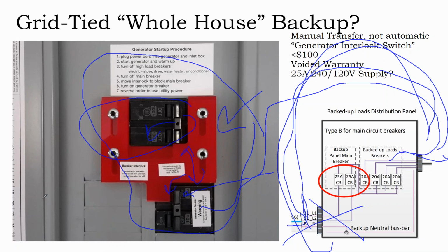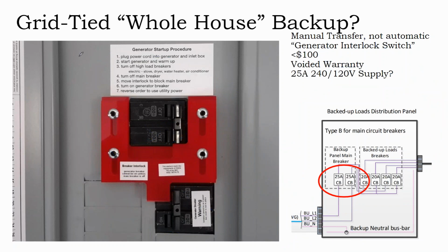But what I would think about in terms of material selection is, when you get to your service panel and you say, okay, my solar array is going down at the bottom of the bus bar, you might also want to reserve the top 2 breaker slots on your service panel for future system expansion, because no bones about it, solar customers want backup power during a blackout, and this is something that's still being established.